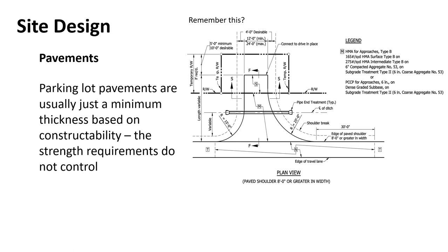What I mean by that is in an asphalt pavement, right? If you've got half-inch aggregate in there, right, you probably don't want, let's say if you got a 1-inch diameter aggregate, you can't do a 1-inch thick pavement layer, right?